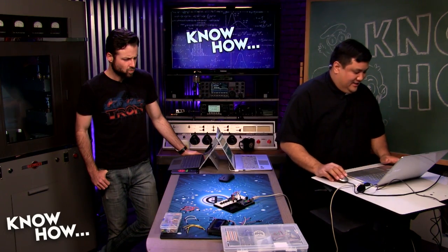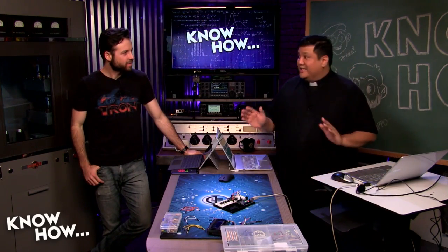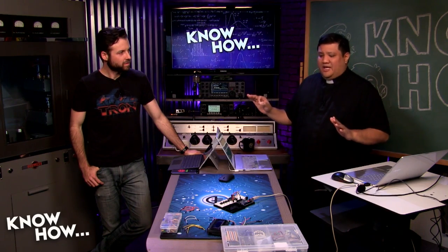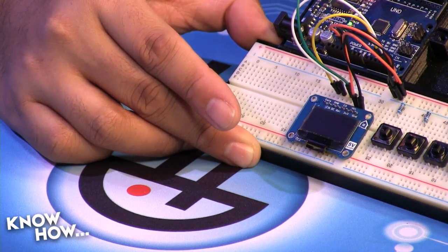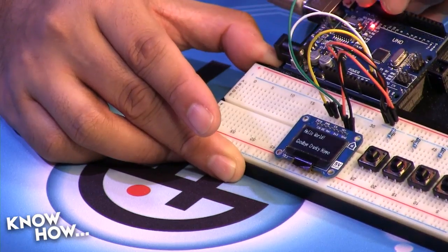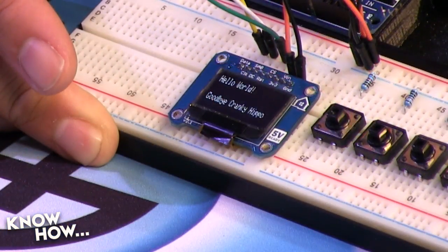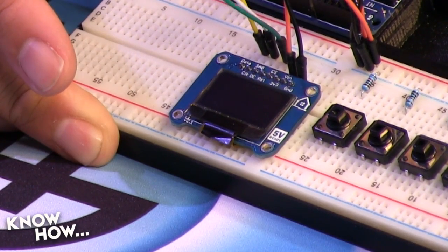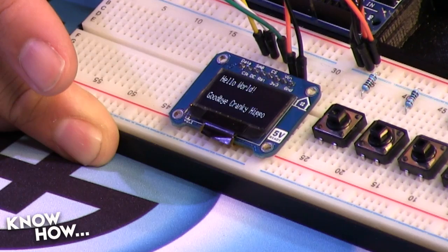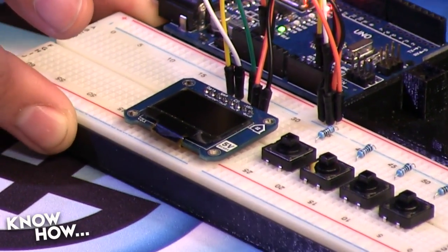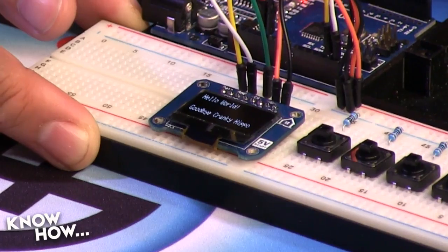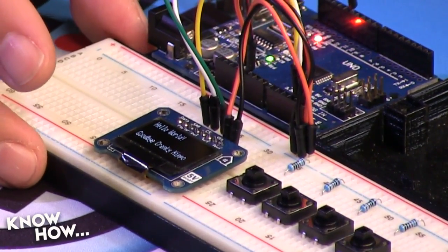Actually, let me change it so that it's not flickering like that. I told you that reset pin wasn't really necessary. It really isn't. 99% of the time you can run without it. There we go. And does it do a little boot up screen too? Yeah, the library does. So I can remove that reset pin, and it still continues to work just fine. If you were to integrate the reset pin, you would just type into the code to send the signal over that, like a data pin almost? Well, it just means that every once in a while it might get stuck in a weird state that it can't recover from, but that is so rare. I think that's happened once in all the time I've been playing with it.